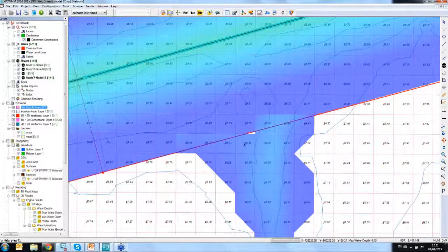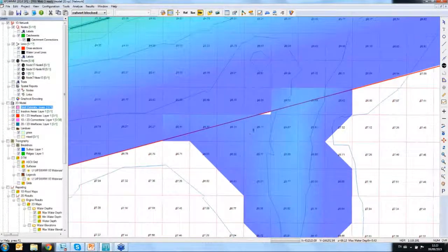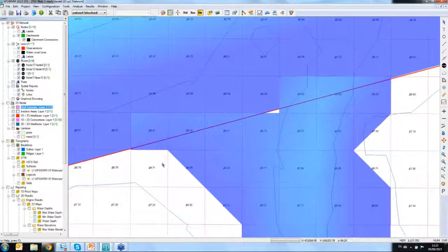Because if we just zoom into any cell of the model, and if I move the mouse down here, there is a Z coordinate, right? And if I move, the Z changes. But what the software does, it calculates or interpolates the average elevation for this 10 by 10 cell. So say if it would be on a very steep slope, 10 by 10 would probably not represent the actual level at that location. So it all depends on topography. Exactly. And the size of the grid.